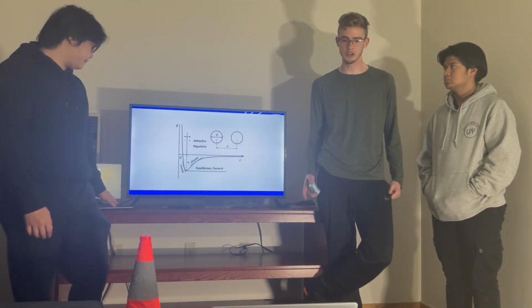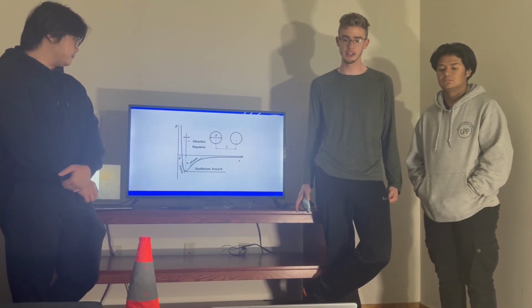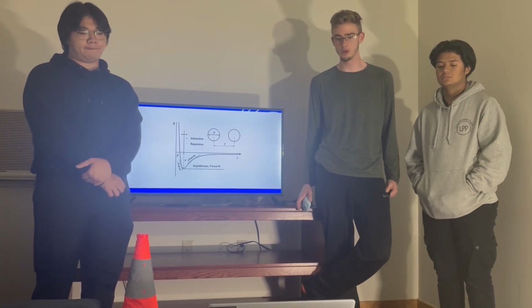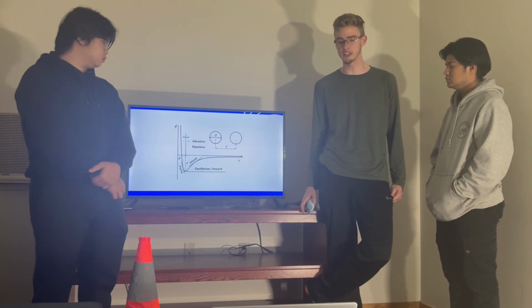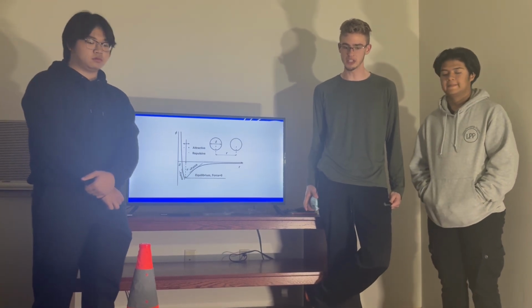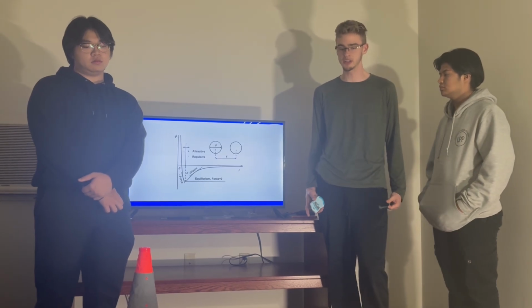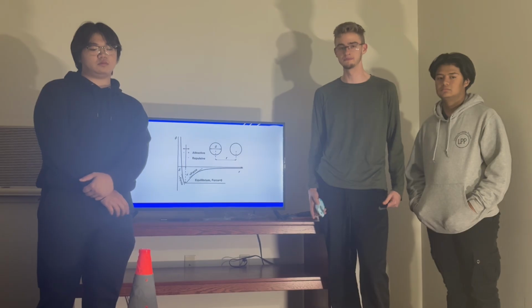So iron's smaller interatomic spacing and steeper energy curve lead to a higher stiffness and strength. In contrast, aluminum, with its lower bonding energy and higher vacancy formation rates, is softer but more ductile. These differences in atomic scale behavior explain why iron is used in load-bearing applications, while aluminum is chosen when low weight and ductility is key.